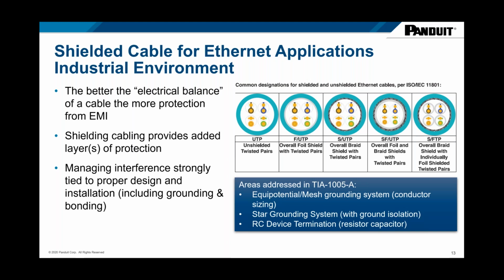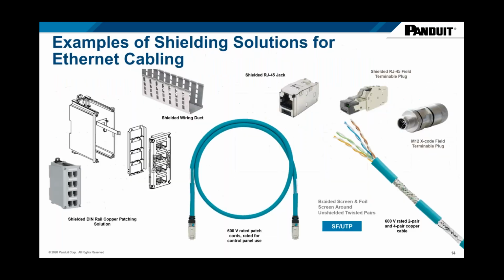We're showing you different types of shielding that are available for the industrial cable types here. So it could be foiled, it could be shielded, it could be shielded, foiled, or screened, many different options available. You could have screening around the individual conductors or pairs, or you could have screening around that entire cable, or you could have both. And that more screened braid of a shield actually helps mitigate that high frequency noise that I was mentioning.